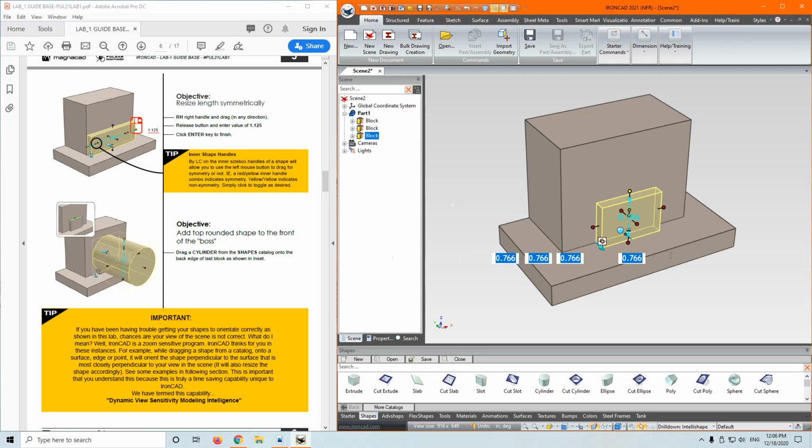And what this tip is telling you is that if you don't like using right click to resize, you can basically change the default, which is set like this. If you click this, the red and yellow, look, you can use the left click now to do it, and it will stay like that permanently.